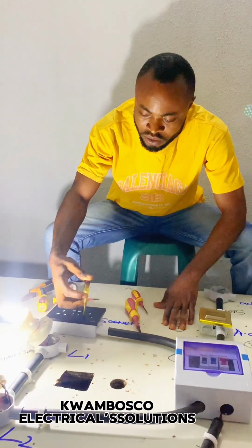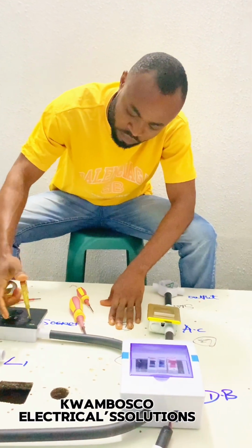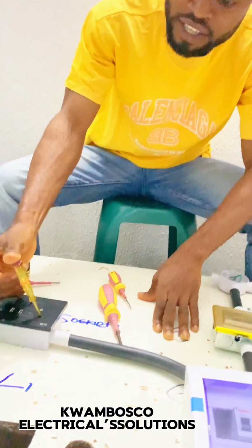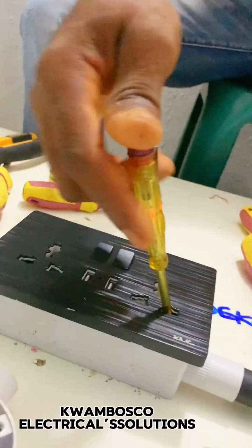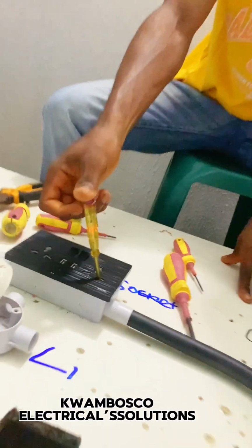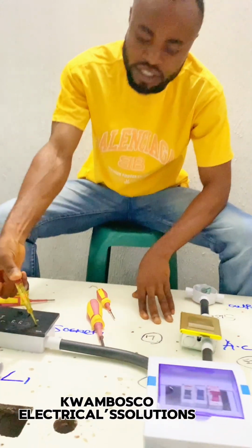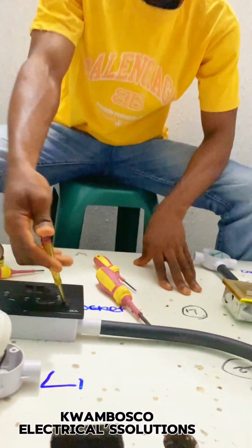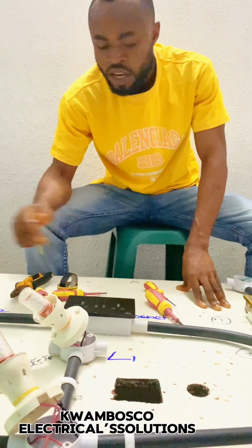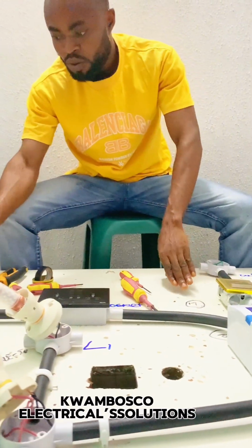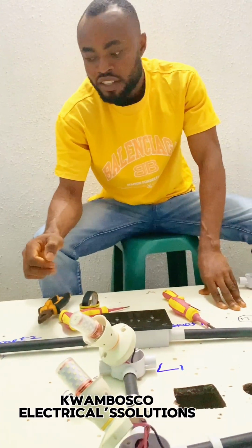Our light, if you look at this tester, you see light here. There's light on this tester. So this side is neutral, that's why it was unable to bring out light. You can see there's light. This tester means there's light. So if I remove my hand, no light. And now I put my hand, the circuit is complete. So if you look very well, now after finishing everything, you realize that your socket is shocking. If your client touches it, the socket is shocking.